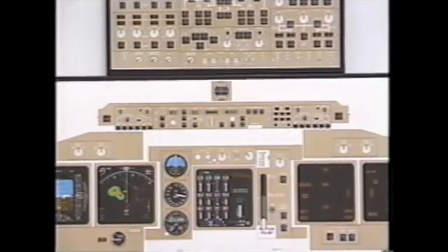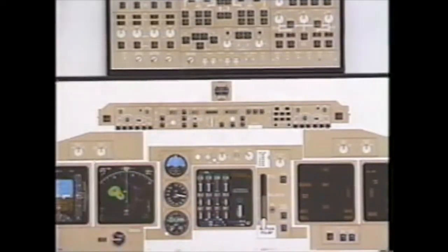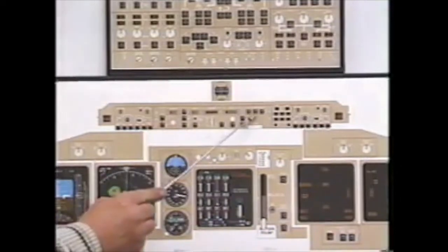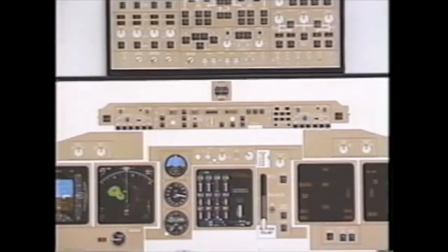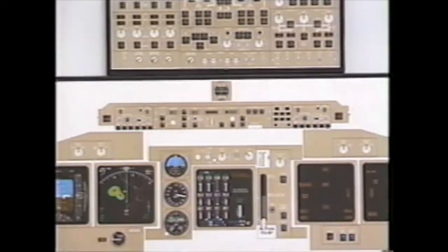Any one of them, pitch or roll, can be used at any one time. Selecting one will disengage the other. There are 3 autopilots, a left, a center, and a right. The left autopilot uses hydraulic system number 3, the left IRS, and AC bus 3. The center autopilot uses hydraulic system number 1, the center IRS, and AC bus number 1. The right autopilot uses hydraulic system number 2, IRS right, and AC bus number 2. Again, the gauge left, center, or right is always 3, 1, 2.